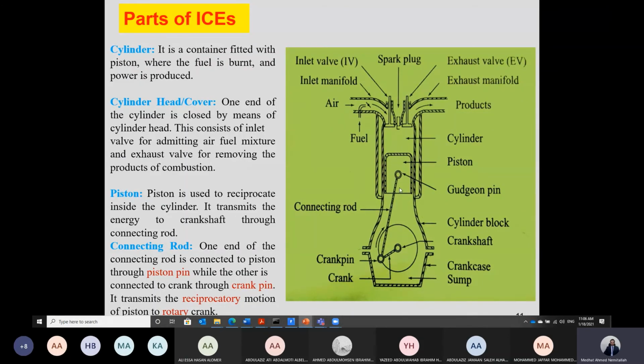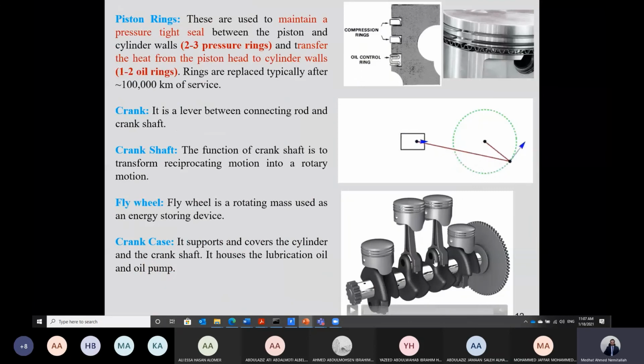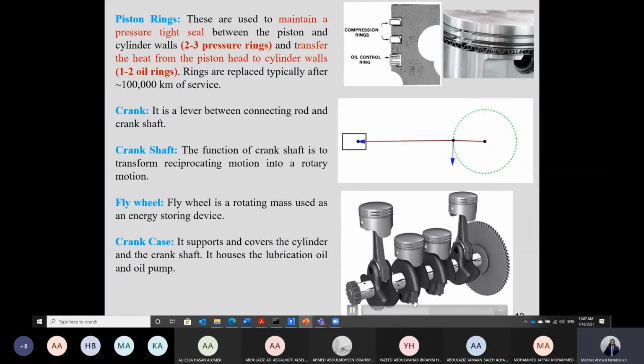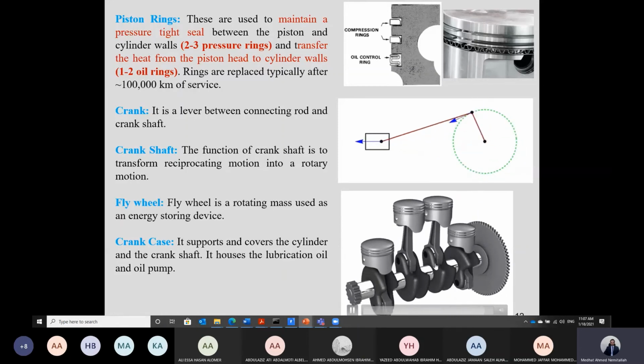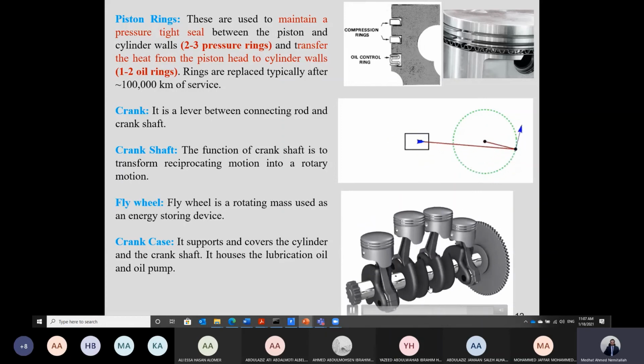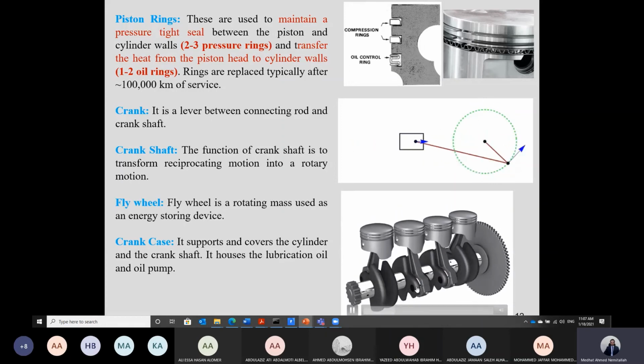And this oil will be coming to the inside part of the piston. The piston, يا شباب, is a hollow part. It is not a solid part. So the oil splashed by the counterbalancing weight will be splashed inside the area inside this piston, just to cool down this piston, and also to lubricate the crankshaft. So while the crankshaft is rotating, it splashes the oil accumulated at the bottom part of the crankcase everywhere, so that it can lubricate the crankshaft.